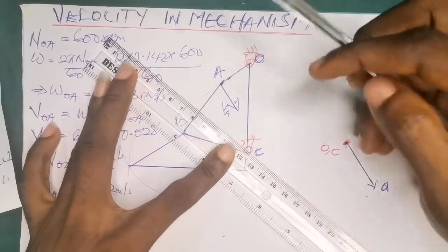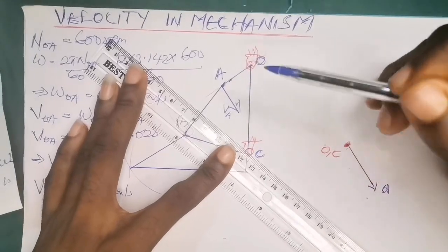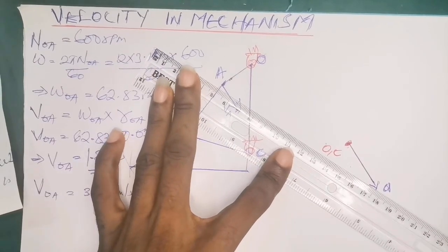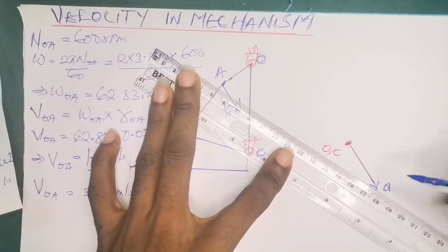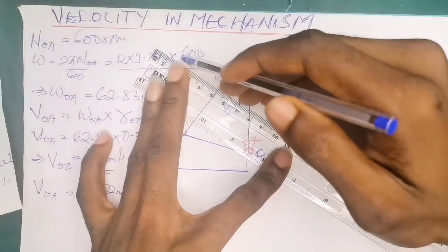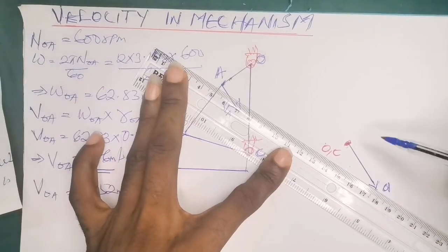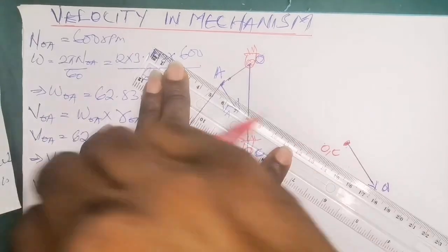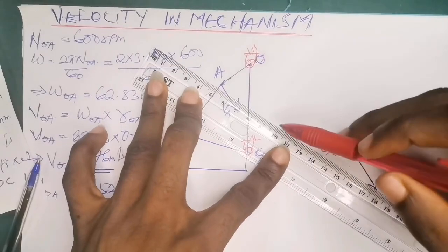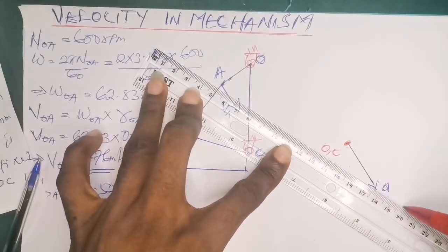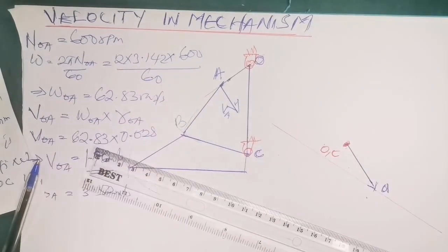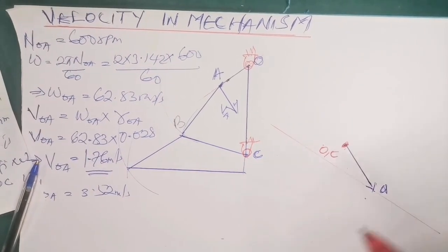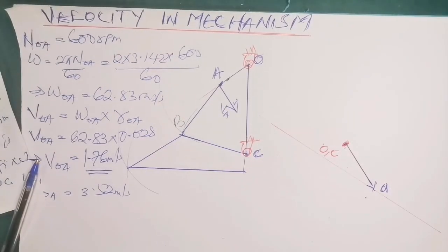So from A to B, you draw a perpendicular line at 90 degrees to this link AB. This is point A, so from point A, 90 degrees to AB. In this case, simply draw a faint line, using a different colored pen, because we don't know the next dimension. We're just tracing 90 degrees from each point.